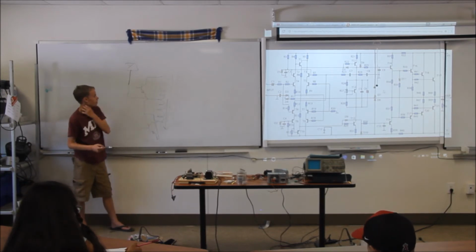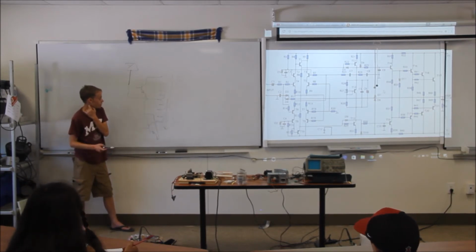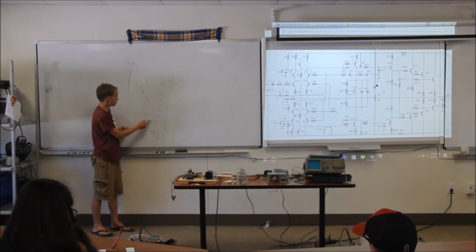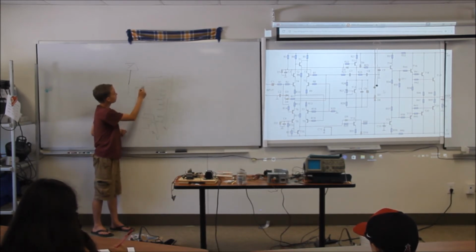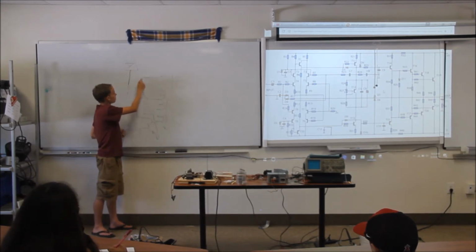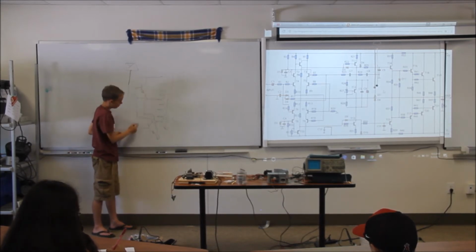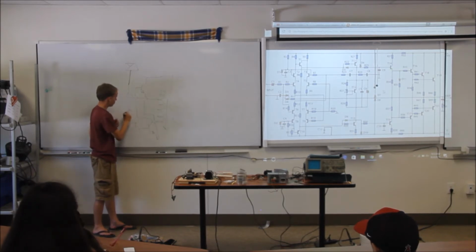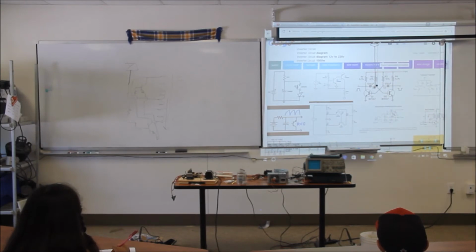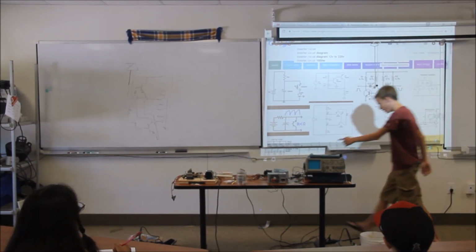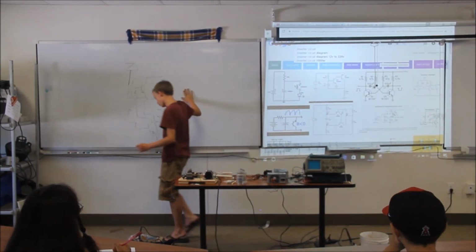Now, how we do this is we're going to use the other transistors to connect to this one. So I'm going to connect this transistor up to here, and this transistor all the way down to here, through resistors on each side, of course, to limit the current so the transistors don't explode. Anyway, it uses two transistors to create a higher voltage on this side of the transformer.